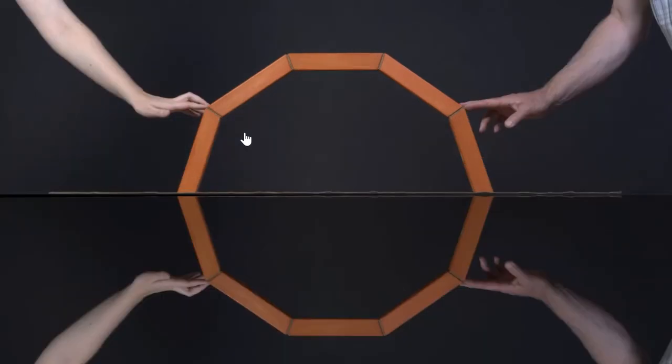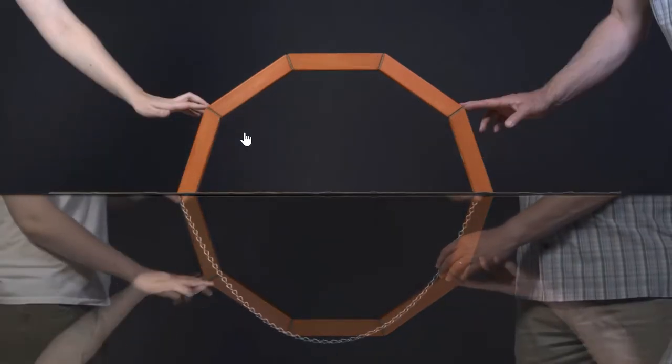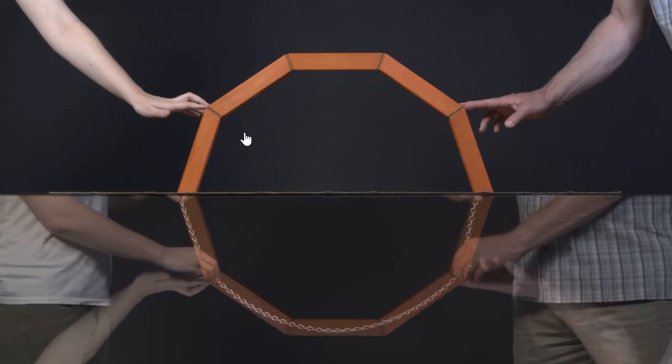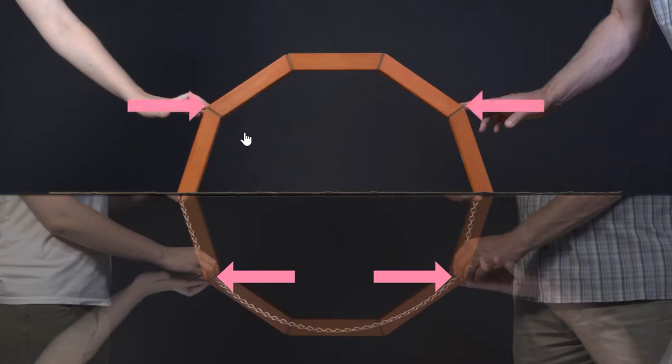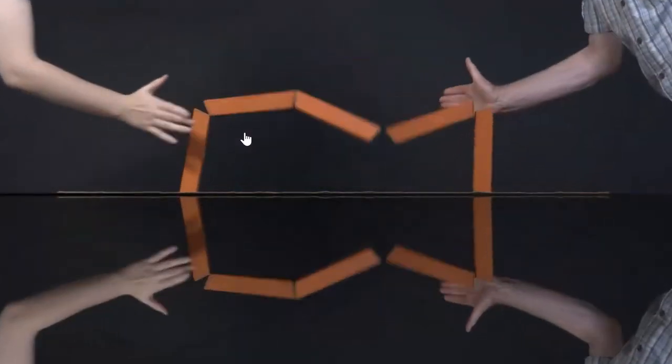Suppose instead that we added forces to the chain to make it follow the shape of the semicircular arch. As you can see, outwards forces applied at these points on the chain would do the job. They change the catenary shape into something more like a semicircle. Recall that a chain is a tension system while an arch is a compression system. Thus, we have to reverse those external chain forces when applying them to the arch. When the appropriate forces are applied to the arch, it stands, and if we take them away, it falls.